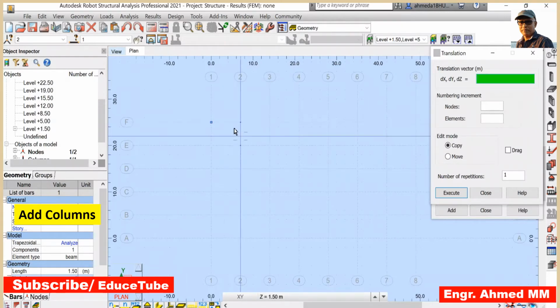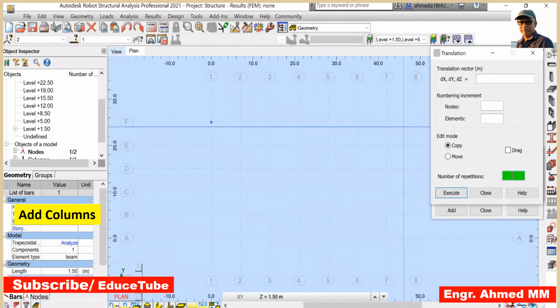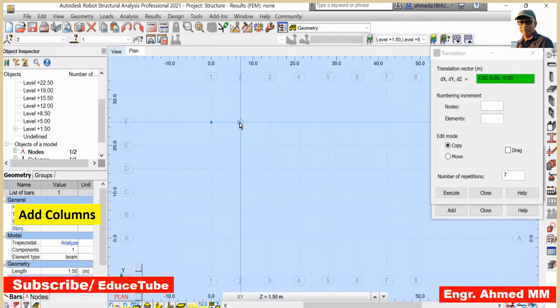So if I want to place this column on this line, it will be repeated 7 times. So I am putting here 7 and make this position active, translation vector. Now it will work. Click here and then here. So you get all.